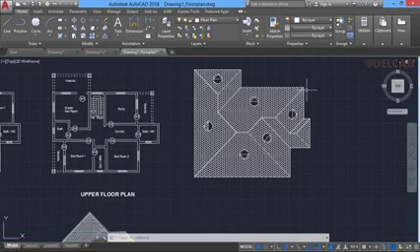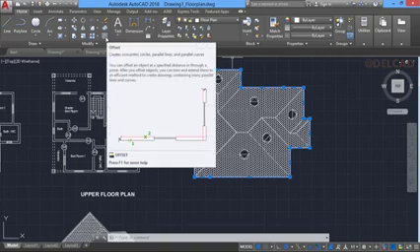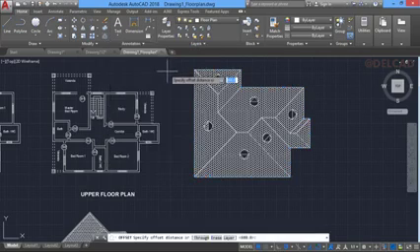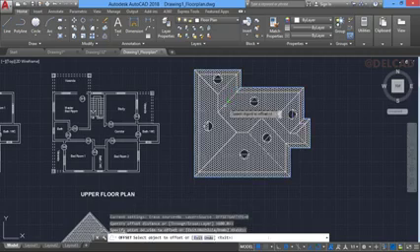So one last thing I want to do is, I have this outer plan which I deleted, so I want to offset it back inside, which is going to serve as the kind of hidden line for the wall. So I select offset and I still have my offset distance of 600, so I press enter and then offset back inside. So you can actually see this.